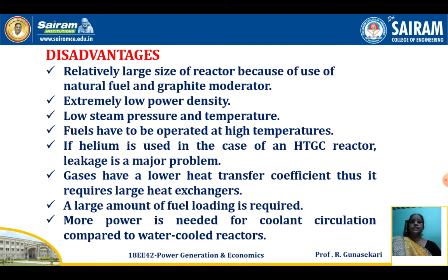Then the disadvantages of gas-cooled reactors. The first one is the large size of the reactor because of the use of natural fuel and graphite moderator. Because graphite is used as a moderator and natural fuel is also used, therefore the size of the reactor is large. Second one is extremely low power density. Third one, low steam pressure and temperature.